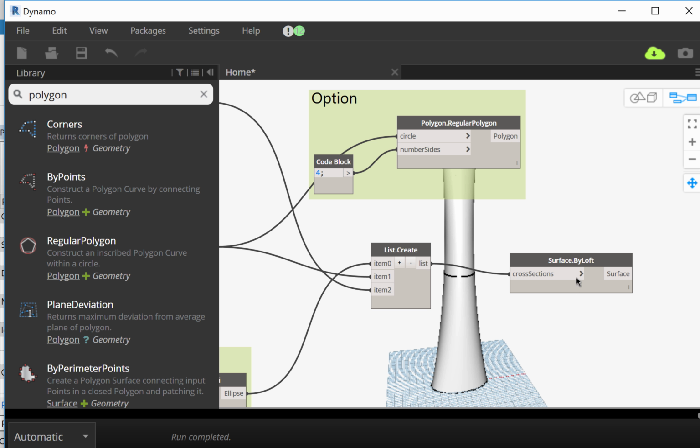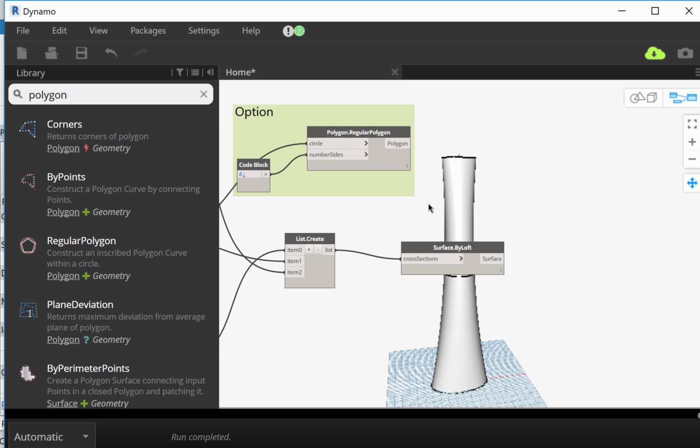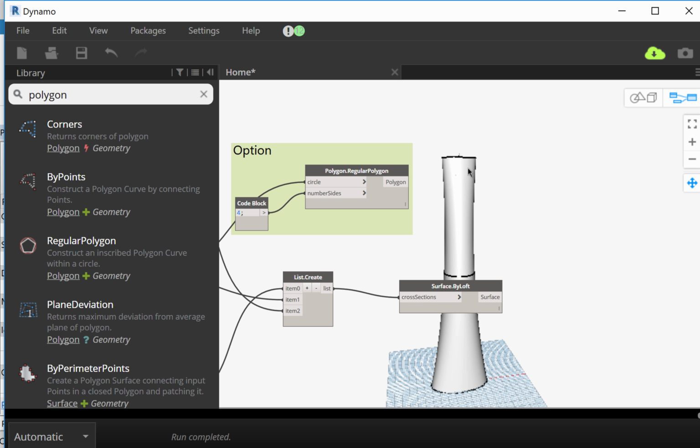All right, next goes the twist. And so the twist can happen, you can pick one of the elements to rotate. You can pick all of them to have different rotations if you want. Like I can pick the bottom profile to have a rotation, or the top one to have a rotation. In my example, I'm just going to have the top be a rotation, but you can choose.